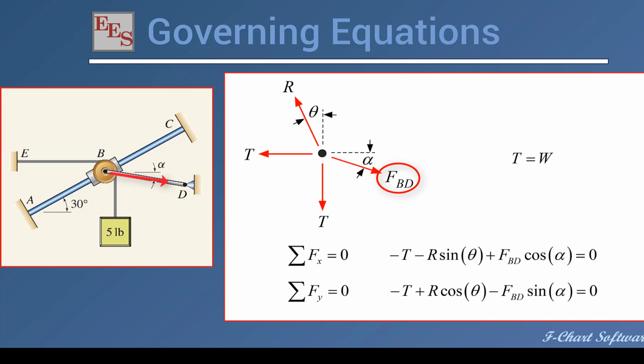And then finally there's a reaction force from the bar onto the collar, and because the bar itself is frictionless, so the collar can slide along the bar without friction, we know that there can be no component to that force that is in the direction of the bar. So the component is only normal to the bar, as I've drawn it here, R. So those are the 4 forces, and